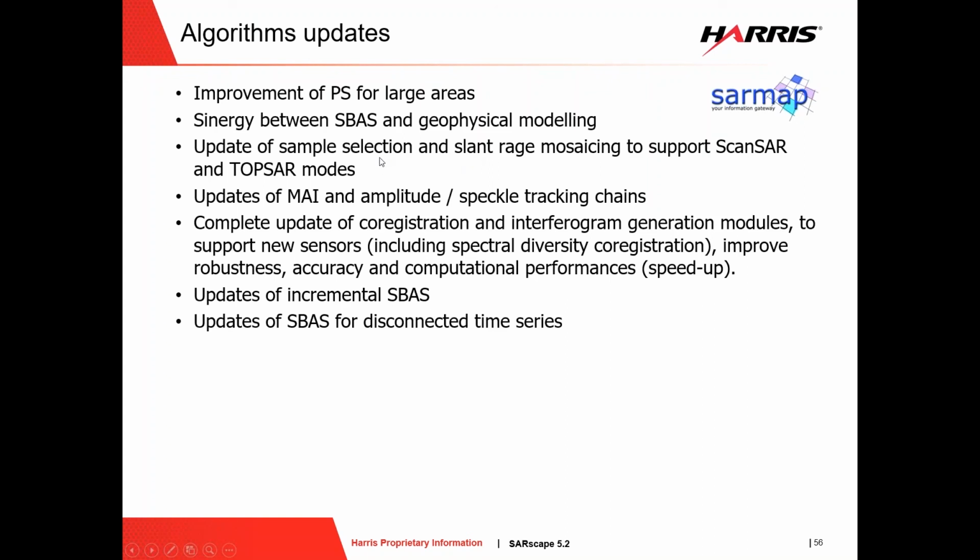As I said, we updated the sample selection and the mosaicing tools to support bursty data, SCANSAR data, TOPSAR data, so you can both subset your SCANSAR and TOPSAR data, SLC data, or mosaic them to cover small or very big areas. Then we updated our multi-aperture interferometry and amplitude tracking chains.